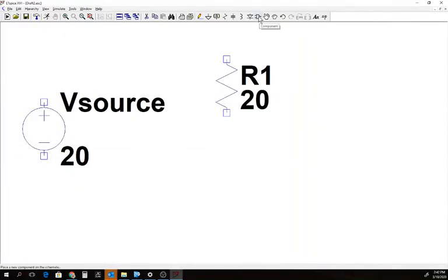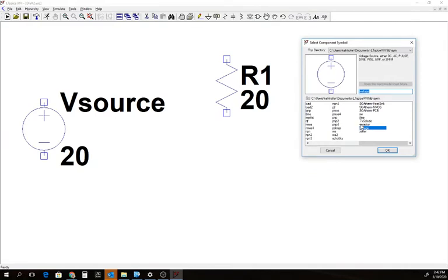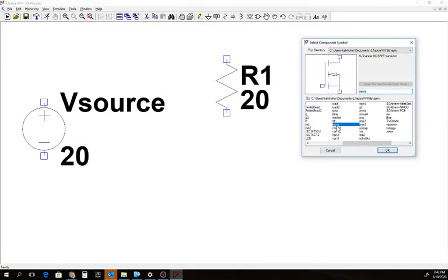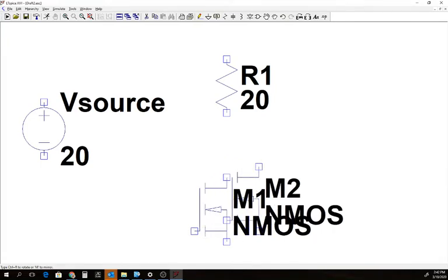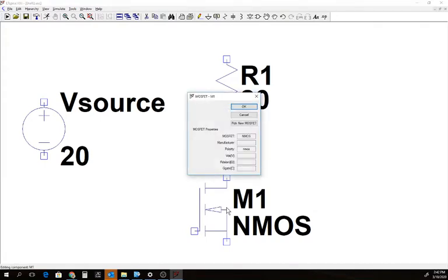To get that MOSFET, I'm going to go up to Component up here. And if we come over, you'll see NMOS. There's NMOS4, which is going to give you the body as a separate connector, but we'll just select NMOS. DC chopper, it's a low side switching topology. And now once I place that there, I've got to select the MOSFET.